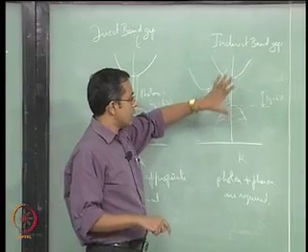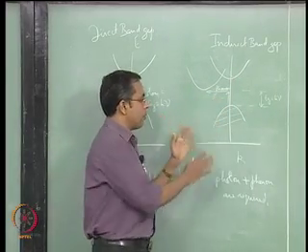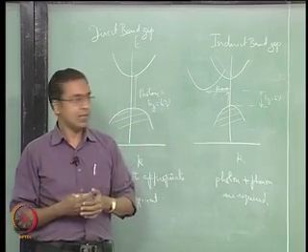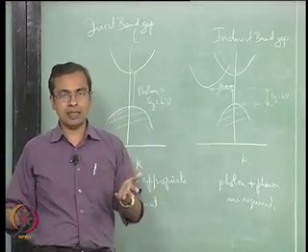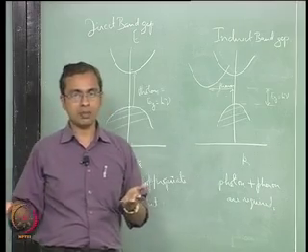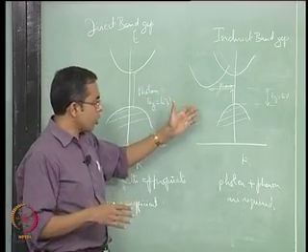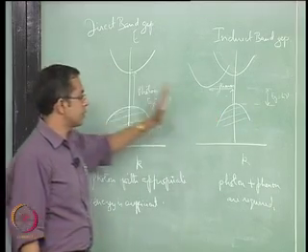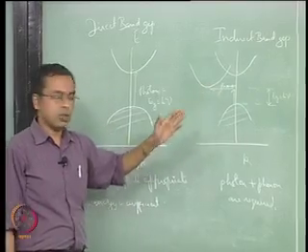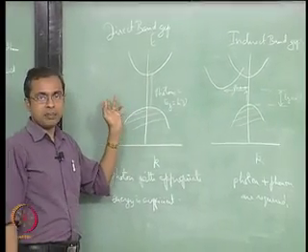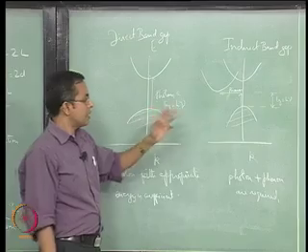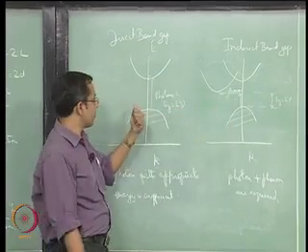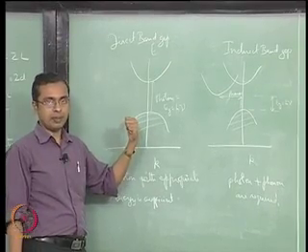So for this kind of process where you are using electronic transitions to get light or interaction with light, these are called optoelectronic materials, okay. So optoelectronic materials is what we are looking at. For optoelectronic materials, direct band gap semiconductors are considered very good as opposed to indirect band gap semiconductors. As we saw in the last class, gallium arsenide is an example of a direct band gap semiconductor, silicon for example is an example of an indirect band gap semiconductor. So for optoelectronic processes you use direct band gap semiconductors, okay.